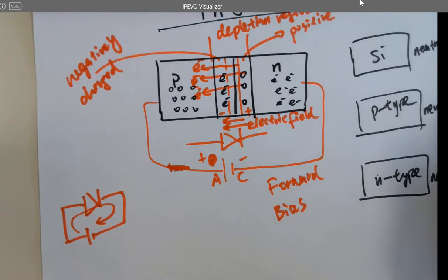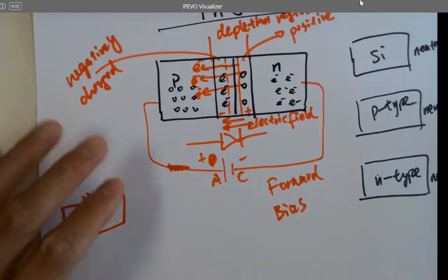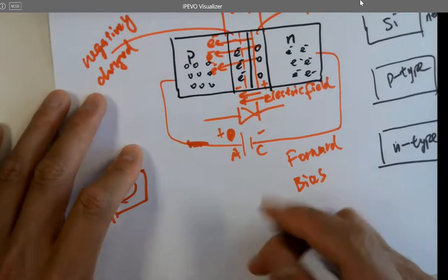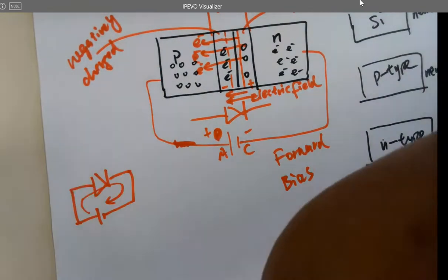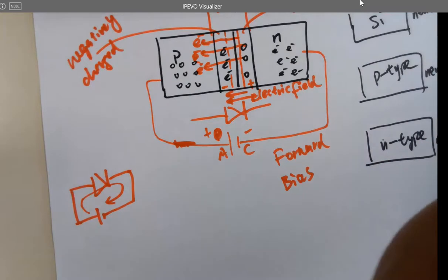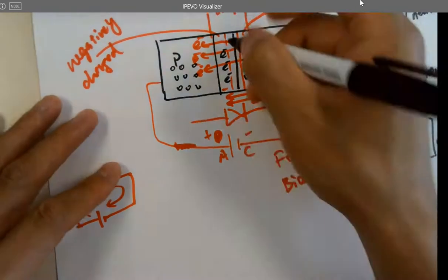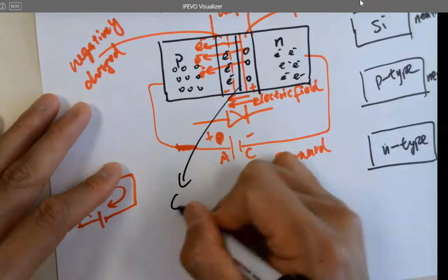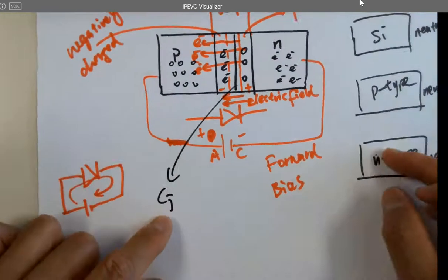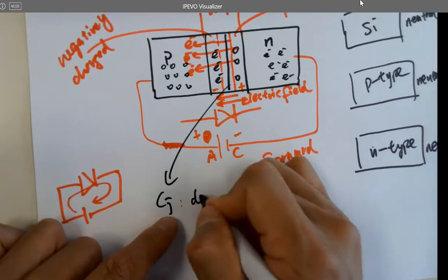One quick question. If you forward bias a PN junction, does the depletion region get thinner or thicker? Thinner. And there's another concept called junction capacitance, or depletion capacitance. Why is there a depletion capacitance over here? CJ, it should be a junction capacitance, just given a different name.